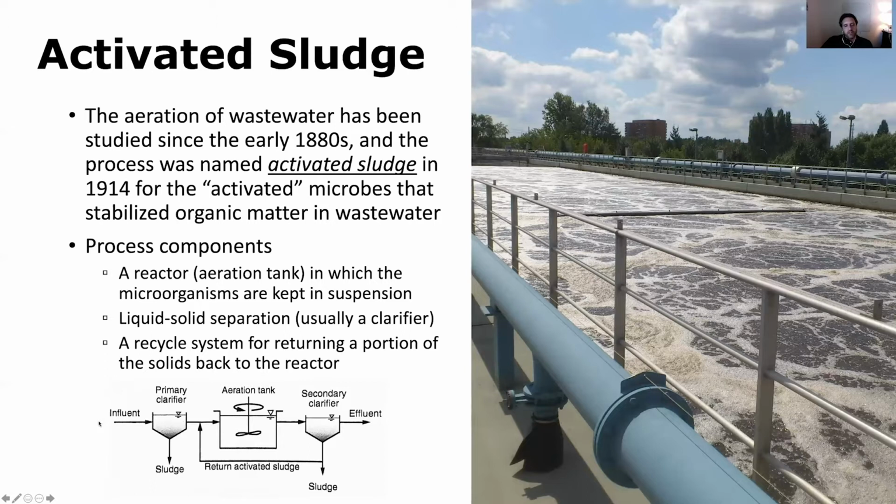So therefore, the hydraulic retention time through this system, or the amount of time that water spends passing through the system, is lower than the solids retention time, or the average amount of time that a microbial cell spends in the system, because we're purposefully settling out those microbial cells and returning them back to the beginning where they can continue doing their work of breaking down that organic matter.